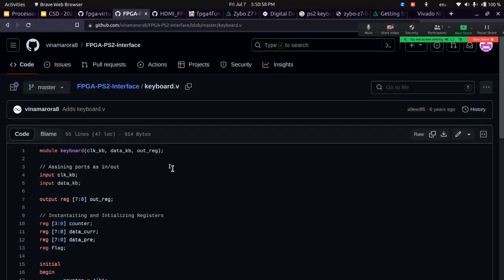So what you can do is have an 8-bit register. Again, it was a design choice, like this is an engineering problem: how do you detect that? So what we did is that there are two things: one is an 8-bit register and one is a 1-bit counter. Every time I read a value, let's say I read a value A, that ASCII code will get stored in this 8-bit register, and that particular counter will be set to 1. That's what you should do.